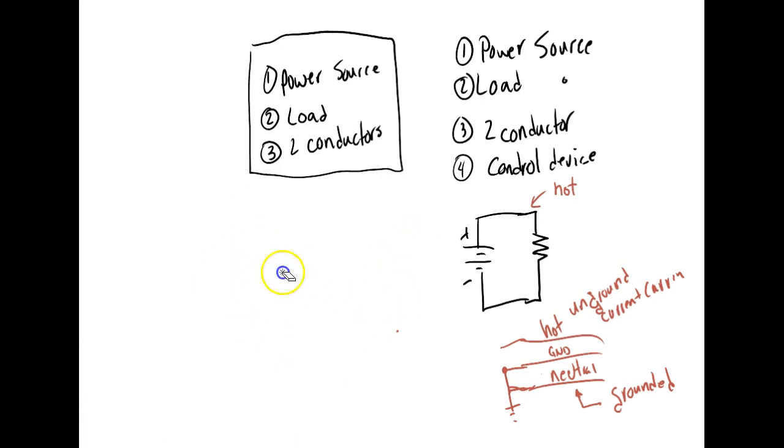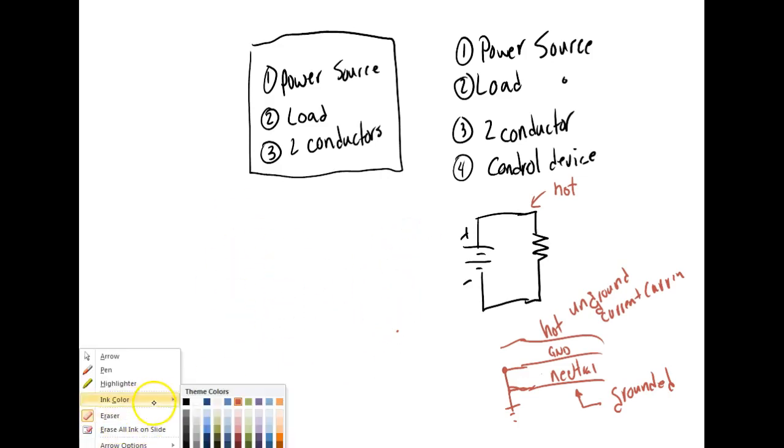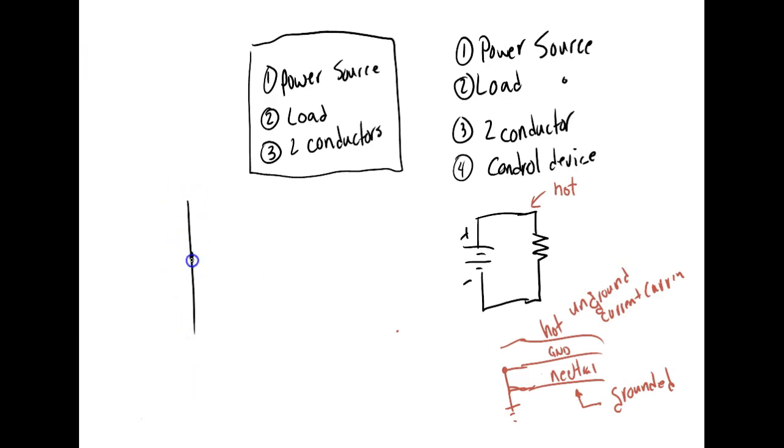Of course, a solid state control device, normally what we do in motor controls is put it inside a diamond shape. So if I see a diamond shape, it means it's what? Solid state. Right, you understand? Now in PLCs, it gets a little more complicated in that they identify what type of control device it is. Then I come up here and put a contact. We usually draw it as a limit switch inside of it. And over here, the load is going to be right here.